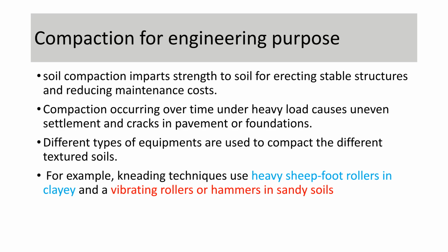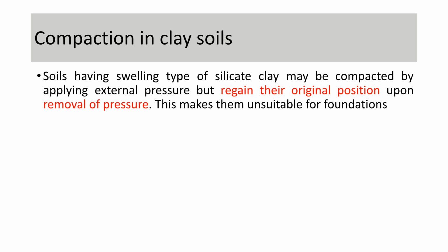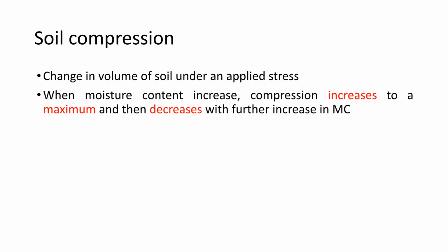Different equipment is used for different soil textures, such as sheepfoot rollers for clayey soils and vibrating rollers for sandy soils. Clay soils with swelling silicate clay are unsuitable for foundations because they tend to return to their original position after external pressure is removed. Soil compression is the change in soil volume under an applied stress. Compression increases with moisture content to a maximum and then decreases with further increases.